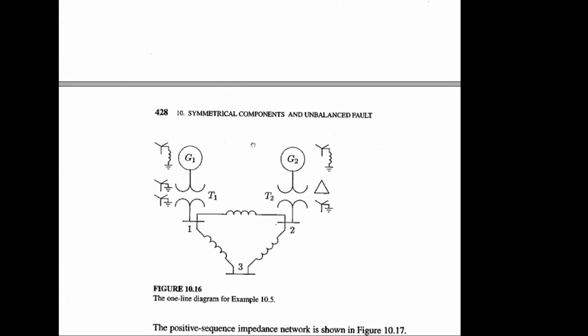Okay, this is the first step to address these types of problem. First step is to generate the equivalent impedance for all the sequences in terms of Thevenin concept. As the bus fault occurs at bus 3, you have to find the equivalent impedance considering bus 3. It might be other bus as well. It might be bus 1 or bus 2 as well.